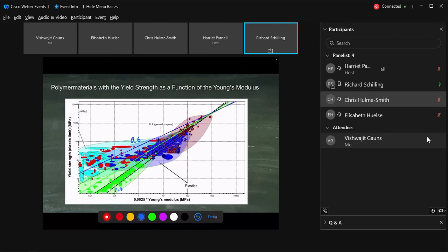So you can go with these parameters, with these fractional powers, directly into your Kohlrausch-Williams-Watts curve, and then you can create all of the time response depending on the stress and times which you want to know about in your application. And that's quite enough for a maker to know. So she or he can find their way forward and choose the materials which they really need.